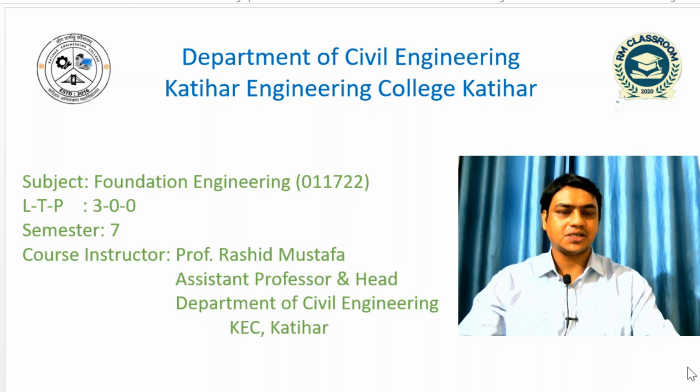So today I will discuss the first one, analytical method. In the analytical method, firstly I will discuss the three modes of failure: general shear failure, local shear failure, and punching shear failure. I will discuss what is general shear failure, what is local shear failure, and what is punching shear failure, one by one in detail. And after that I will discuss Terzaghi's method to compute the bearing capacity of soil, with its various assumptions.